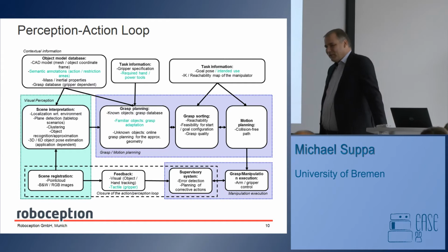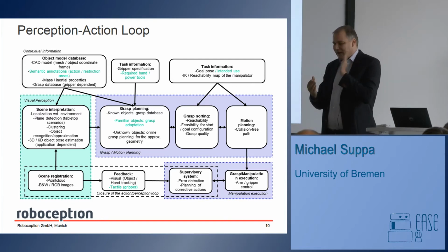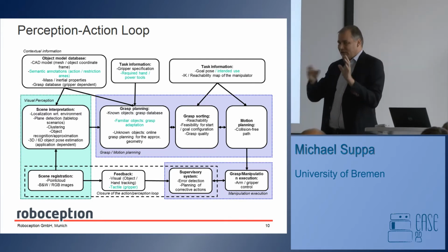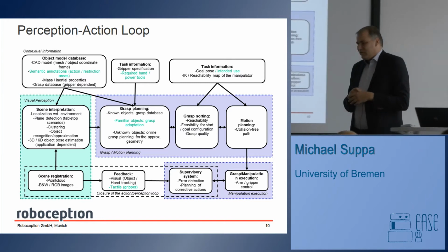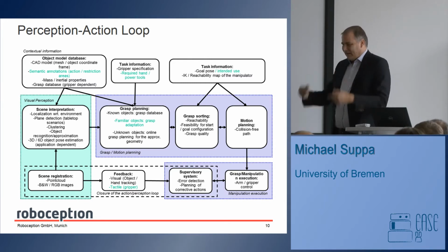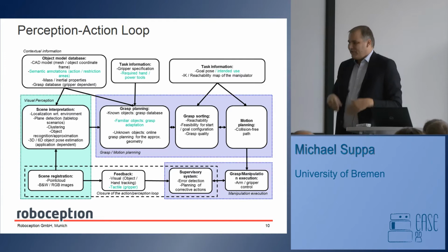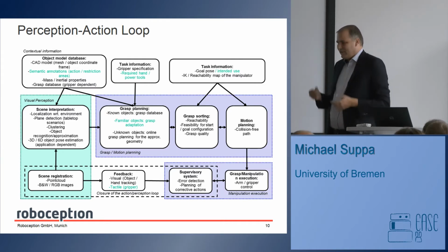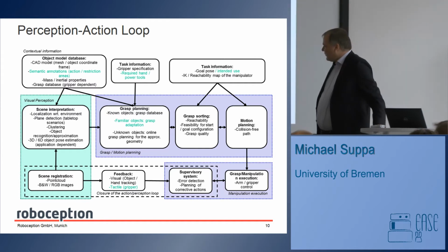Now envision doing that with a robot, all the small corrections that you do every time, because you're only interested in the relative position between your eyes, your hand, and the object. It's all relative. Most robots work on a global coordinate frame. So they have a base coordinate system somewhere. And until you go to this relative movement, you have a lot of calibration error and all that stuff that we don't have. We can do this all directly.